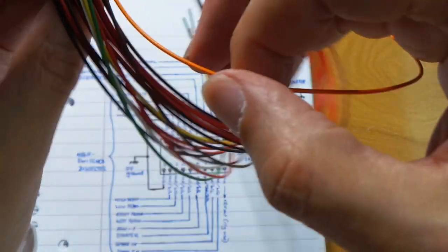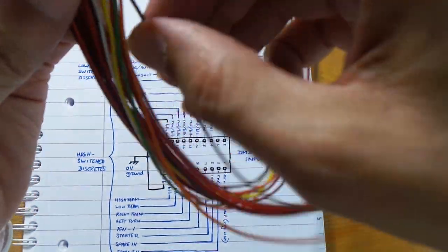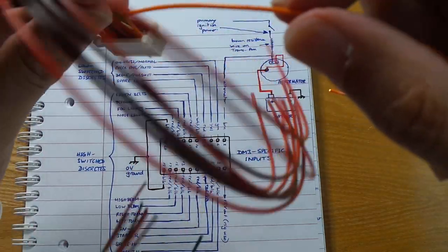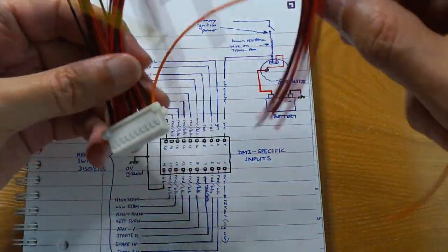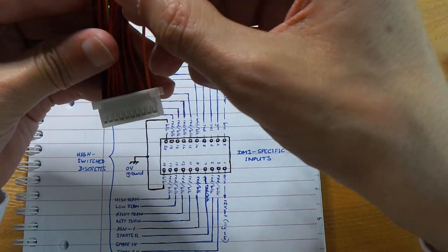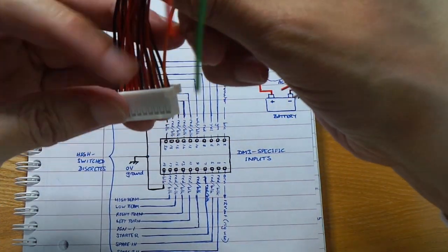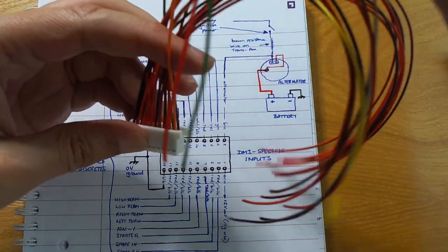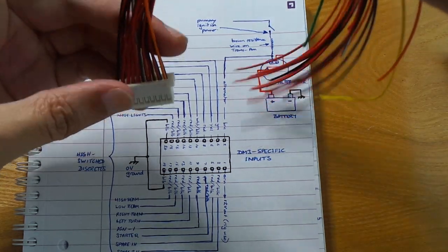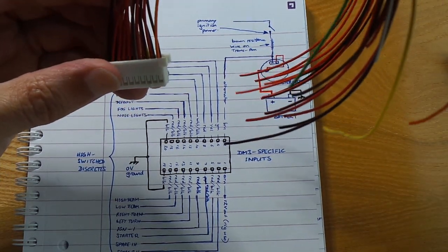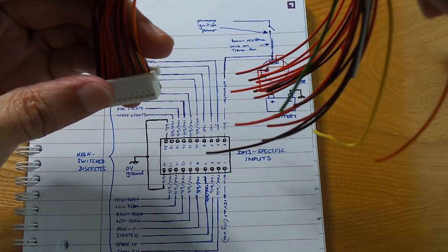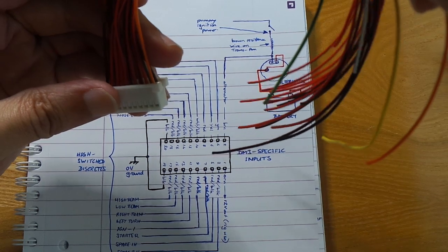Pin number 1 is an orange wire, which is at the bottom row and the right hand pin, and this is a 12 volt connection, which is a 12 volt output from the dash module number 3, and you probably won't use this. The main reason for this is to enable us to test the unit easily on our test bench, because this puts out a 12-volt signal, so that enables us to drive switches which represent high switched inputs.